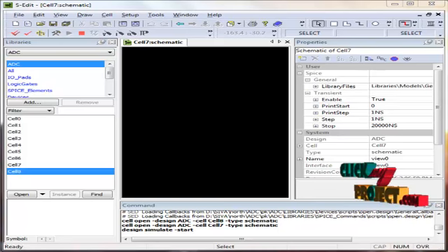The 6-bit DAC is based on the charge scaling split array method. The block diagram of a 6-bit charge scaling DAC using the split array represents the circuit that converts a 6-bit digital input to a respective analog signal by scaling a voltage reference that is obtained by the capacitive network. Various building blocks of the DAC are the operational amplifier, capacitive network, and multiplexer switches to the digital word.